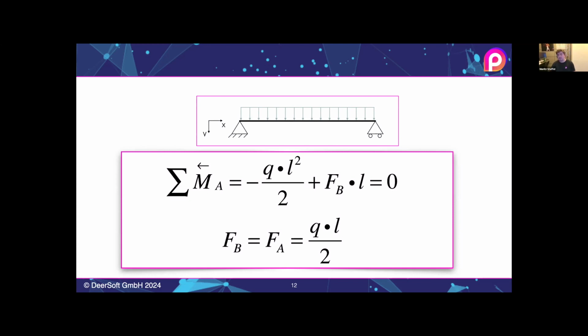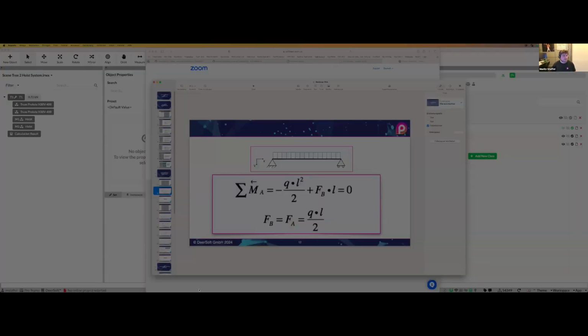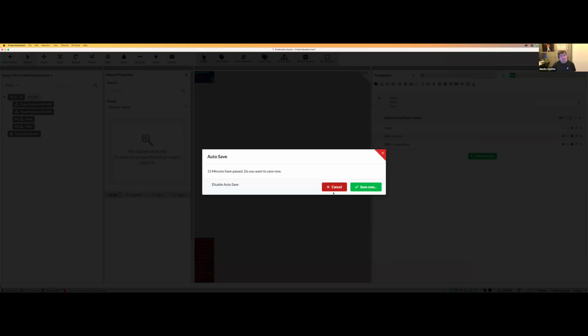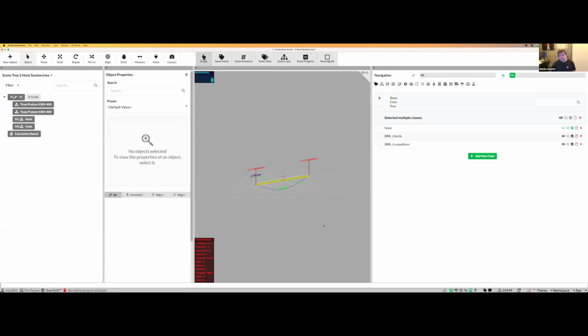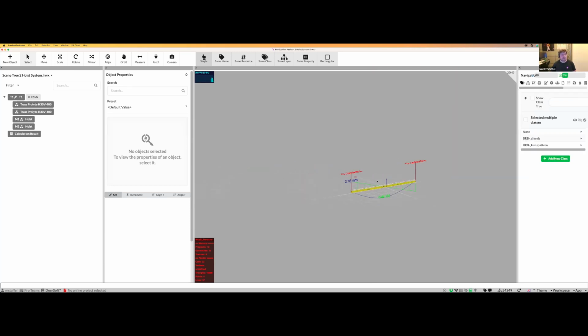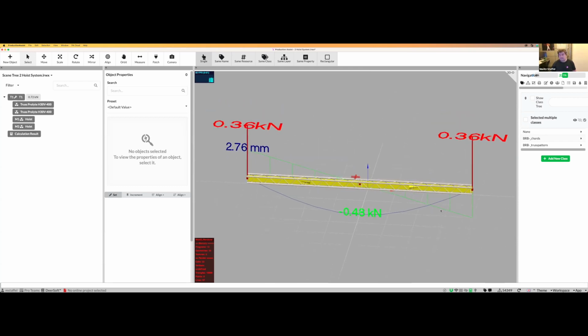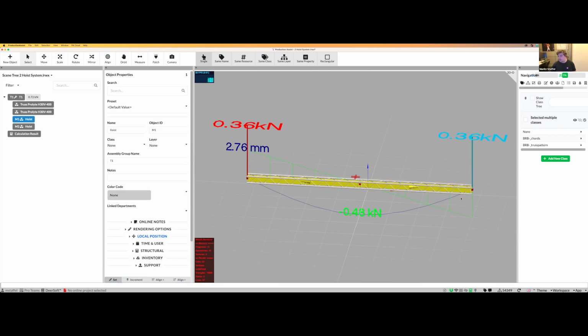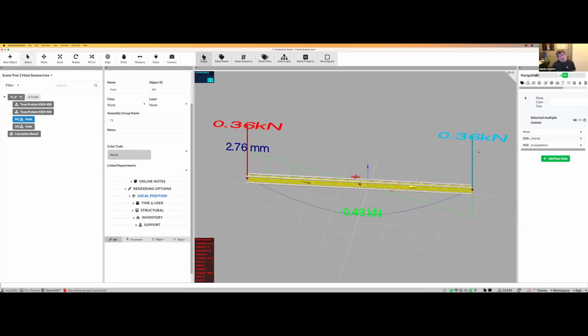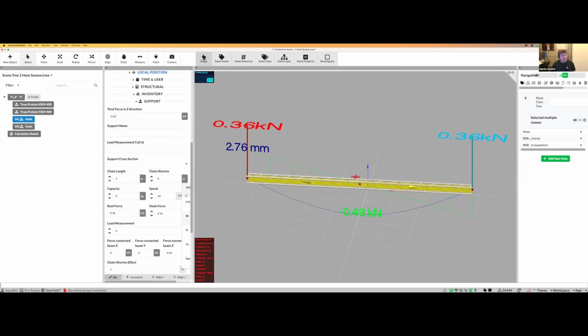This is something we do hands-on in order to jump into the first example. I have the exact same system that we also have with the other parts. I just make this a little bit larger. And we see that it's really 50% to the left and 50% to the right. So the interesting question that we now are asking ourselves is, what happens if we move up this hoist a little bit? For this, I go onto the support, click onto the supporting properties of the first hoist, and go to the chain shorten.